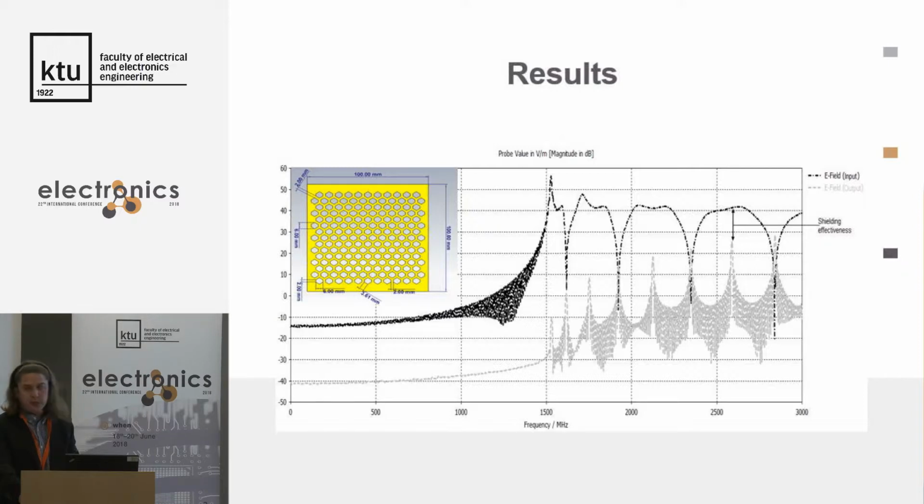The last figure illustrates the electric field detected by a probe behind a shield with honeycomb holes. This variant recorded the worst results, but in comparison with rectangular holes, the differences are negligible. The visibility is better than the shield with circular holes, but worse than the one with rectangular holes. This variant looks like the least suitable for lens protection purposes.